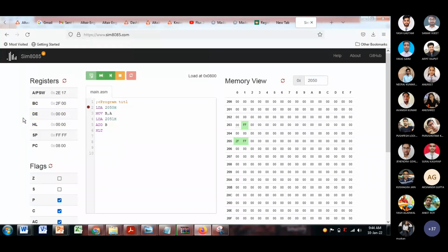These 6 registers are general purpose registers. Sometimes there is a carry and we need 16-bit information to store. Because generally each register is defined by 8 bits, B is 8-bit and C is 8-bit, we also use register pairs for storing 16-bit data.